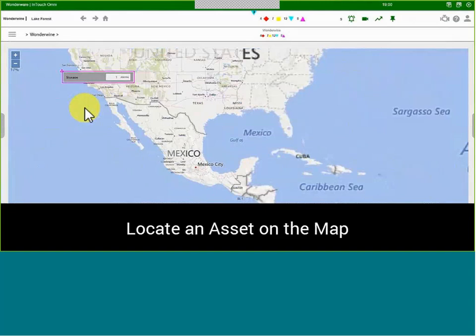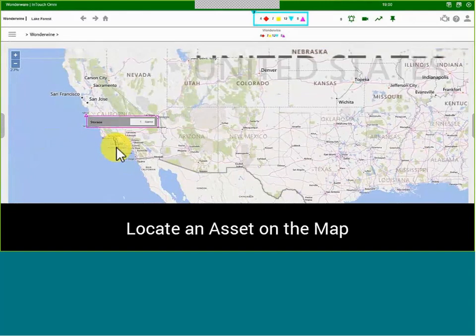Then if we have a look at the maps, you can locate the asset, and you could argue that you can put a map into any SCADA, and that is true, but the difference here is that you can actually dynamically change it and it automatically updates. So you could certainly put a static image inside of InTouch, and you could put graphics where you want them to reside, but you then couldn't zoom into where that map was. What we've done here is added the architecture graphics based on coordinates in terms of the map. It uses things like open maps to display those maps, and when you zoom in you get a different level of granularity. So I can choose at different zoom levels how much data I want to see.